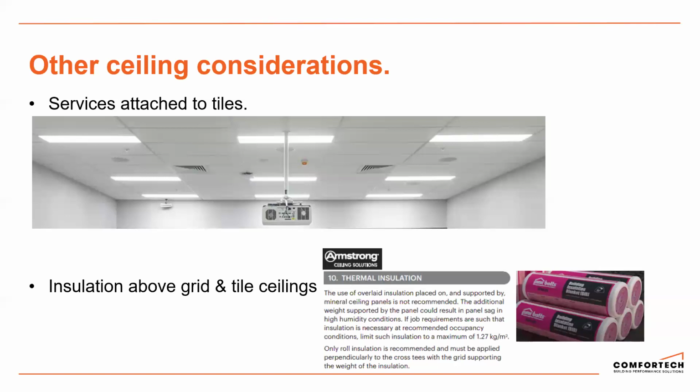It's also really important that when we are attaching things to the ceiling grid, we utilize the back of the grid. We don't want to be attaching things to the bottom of the grid. We often see different ranges of products out there that are designed to be attached to the bottom of the ceiling grid, whether it be baffles or light fixtures. The problem with doing this is it can void manufacturer's warranties.